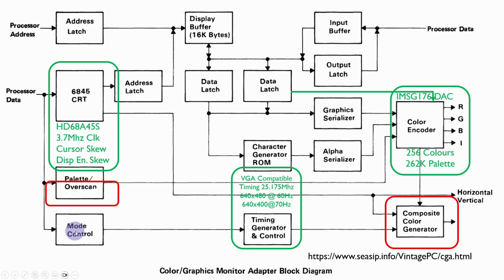The mode control controls the various video modes. The timing is going to be changed from the CGA timing to VGA timing, so there's quite a few changes in this area. And what this will also mean is we won't really be able to use some of the CGA specific test utilities that rely on very accurate timings, because the timings here will be quite different from CGA, although the output will be compatible.